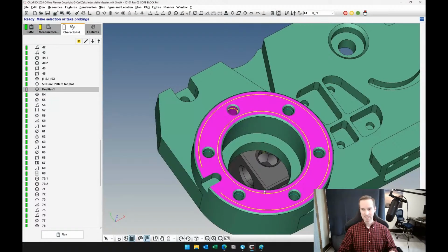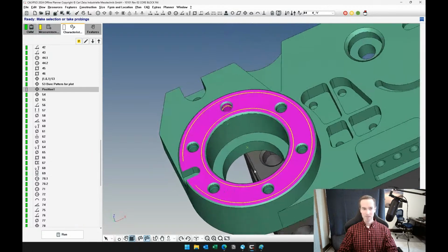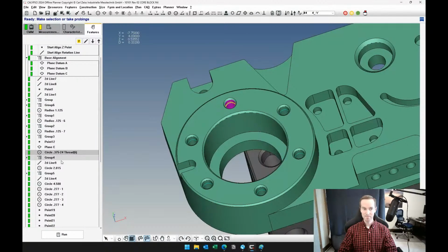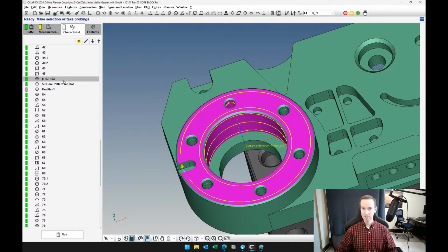Okay. All right. So that's composite in a nutshell. You can do the features as a pattern like I did here as far as programming them, or you can put them in separate. The advantage of doing it as a pattern is just quicker, but there is a disadvantage. You don't get to see every result in your program right away, but they will show up in the report. That's why you have this, says 1, 6, 1. It means it's a pattern with 6 features.